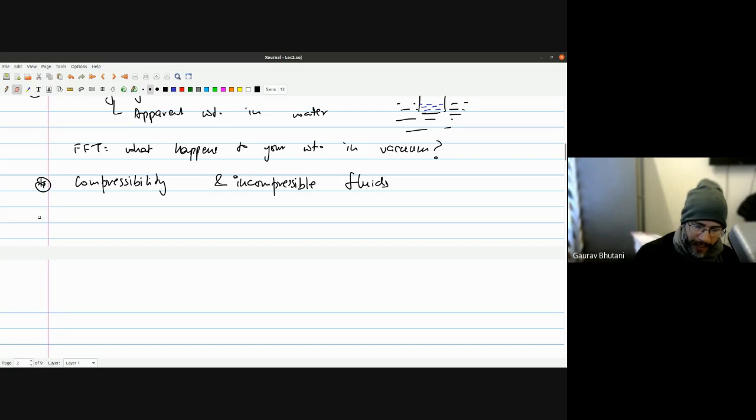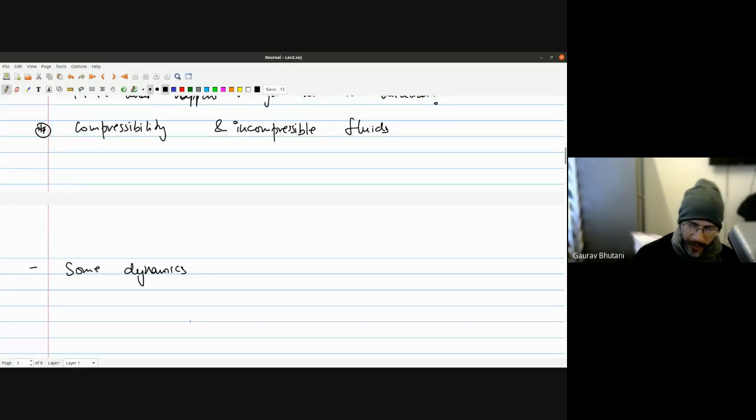Then you have done some dynamics as well. In dynamics, you talked about the idea of viscosity, where a relation called shear stress tau is equal to a coefficient mu, the coefficient of viscosity, times du by dy. So what we're talking about here is that this tau is the shear force acting per unit area.